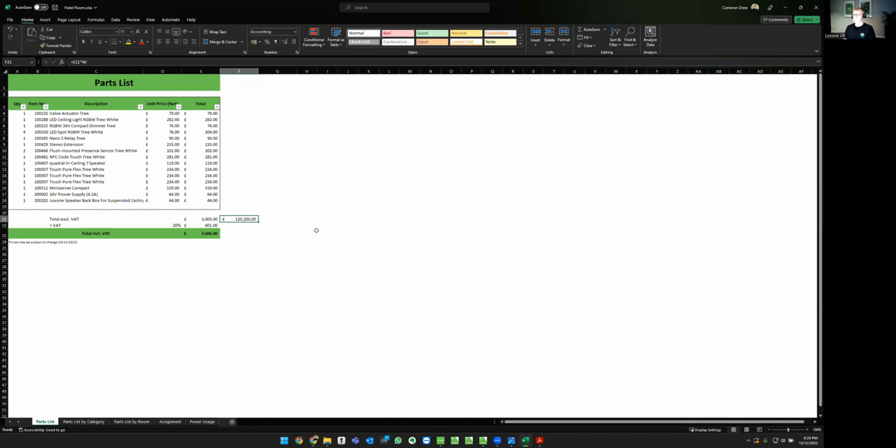So you're constantly heating a room for literally no purpose. Whereas with Loxone, of course, we don't need to do that. And the way that we know that a guest has booked is because we can integrate with a hotel management or hotel booking system. And they can, for example, assign a room, and then the mini server will also automatically make sure that that room is up to the correct temperature when it should be.